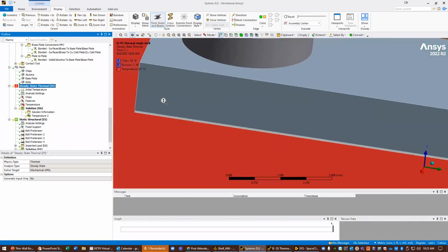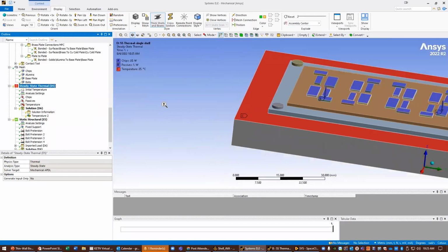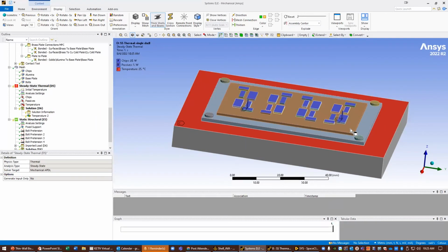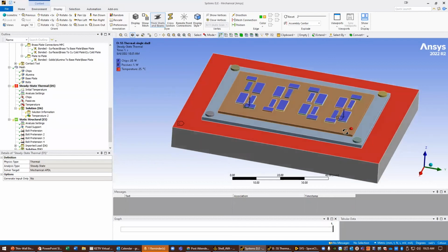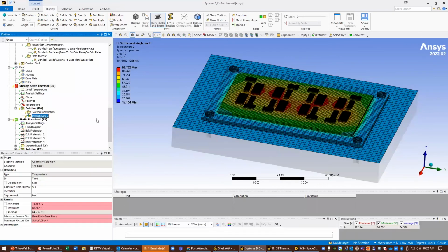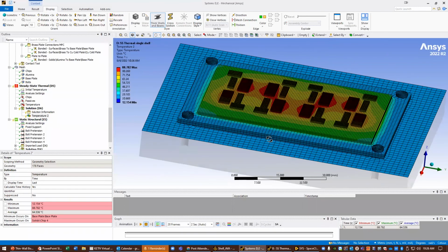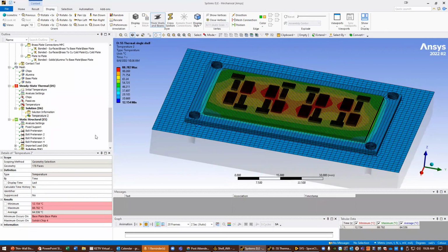For the steady state thermal analysis that we were doing here, I was putting some extra heat in to represent the chips and what kind of heat they're exerting, what kind of heat's coming out of them, and then doing a cold plate here, holding it at a constant 25 degrees to get our thermal profile of what this system is looking like.